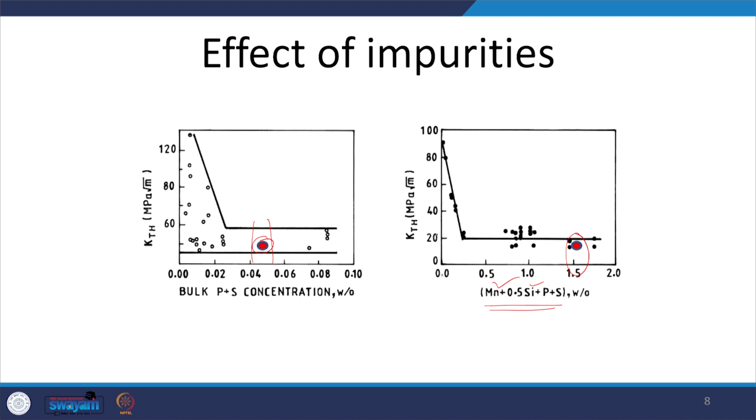Okay. So, the steel on its own may be having, like say, 80 or 100 fracture toughness in terms of the stress intensity factor, but when the concentration of these impurities is high, this decreases the fracture toughness significantly. It means if there are defects and discontinuities, then under the tensile stresses those will be propagating very easily and causing the opening of a crack or even fracture. Okay. So, higher concentration of these impurities is one of the possibilities which can lead to the cracking of the steel when subject to deformation.